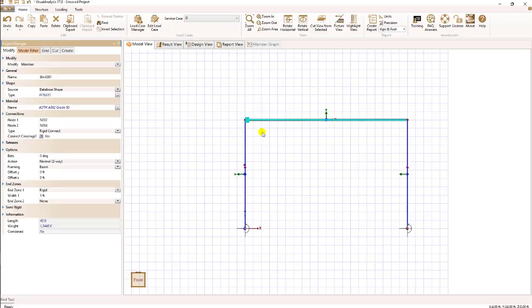A reason you might do this is if, say, the concrete column was connected to by a steel beam and we had a shear plate welded and the beam welded to the shear plate, and that was offset by half the column distance. So to do that, then I would enter an end zone 1 foot.